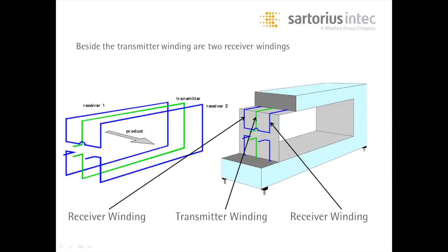You may have noticed that many metal detectors are quite heavy and bulky, and the reason is they need to be filled with something very solid. Some companies use epoxy, some companies use concrete, I've heard, but other companies have different technologies for filling the coils. The reason is you don't want these windings to move. They have to be very stable, and the positioning of them has to be fixed.